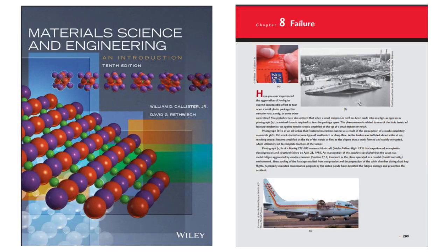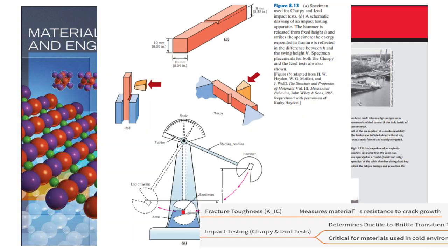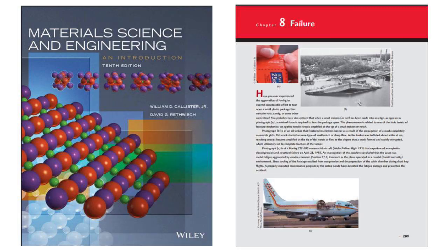The textbook also talks about impact testing. So like the Charpy and the Izod tests? Yes, those are classic impact tests. What do they tell us? So they don't give us a precise fracture toughness value like K IC, but they give us really valuable insights into a material's tendency to fracture in a brittle or a ductile manner, especially at different temperatures. So it's like seeing how the material reacts under pressure, literally.